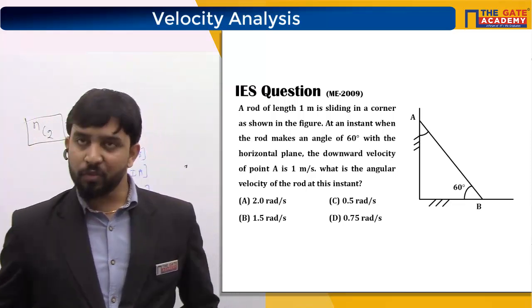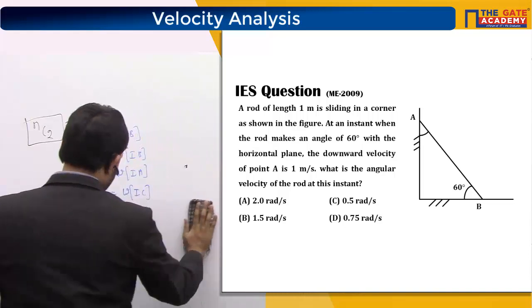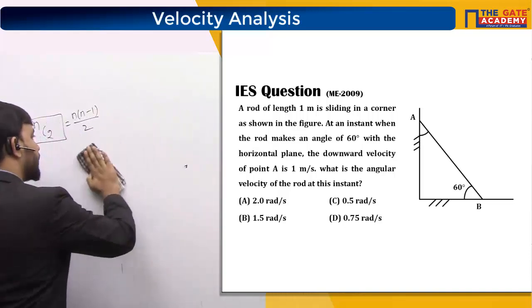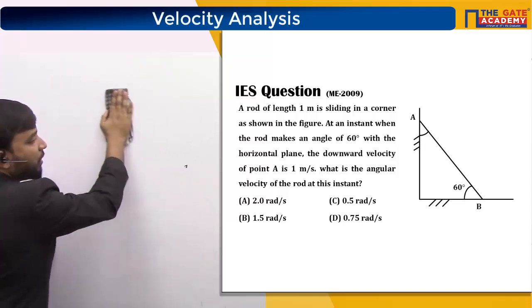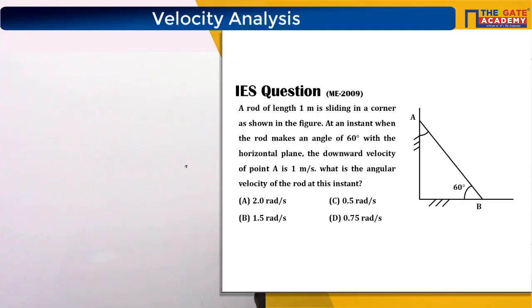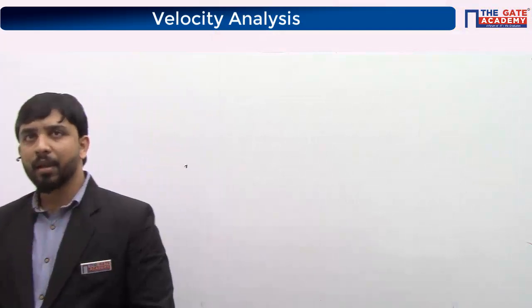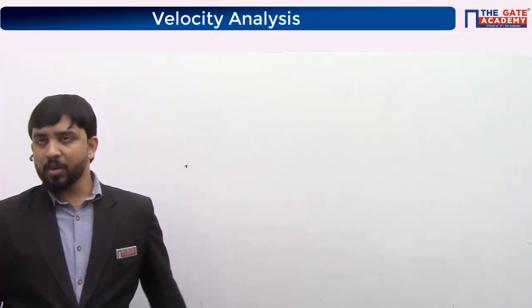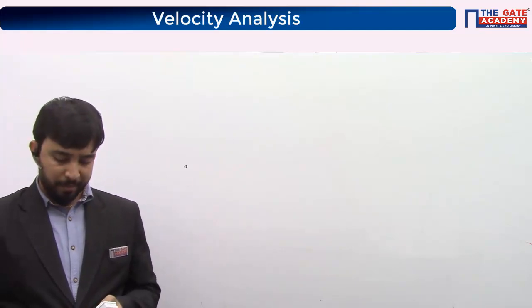So whenever they ask you to find out angular velocities of links, you have to look at center of rotation, okay? So center of rotation is instantaneous center of rotation. If you know center of rotation, then we have seen some properties for centers of rotational motions. They are applicable here, okay? Yeah, what's the answer for this? Just look at this question.